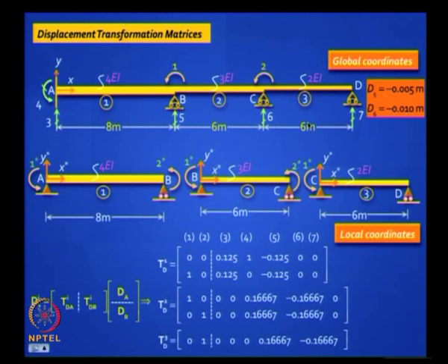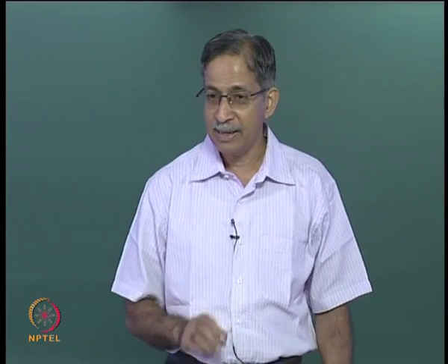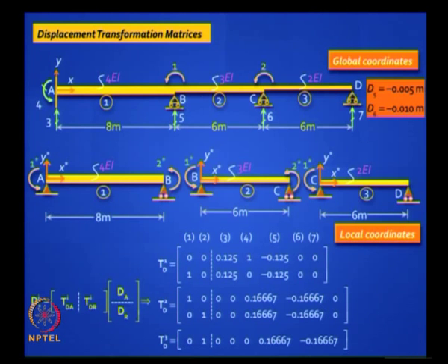Let's look at the last one. Let's say D7 equal to 1. If you lift up the last one, only element 3 will be affected. Agreed? Only element 3 will be affected. You have a clockwise or anti-clockwise chord rotation? You have an anti-clockwise chord rotation, and the equivalent flexural rotation will be clockwise, which means negative, and it will be 1 divided by 6.